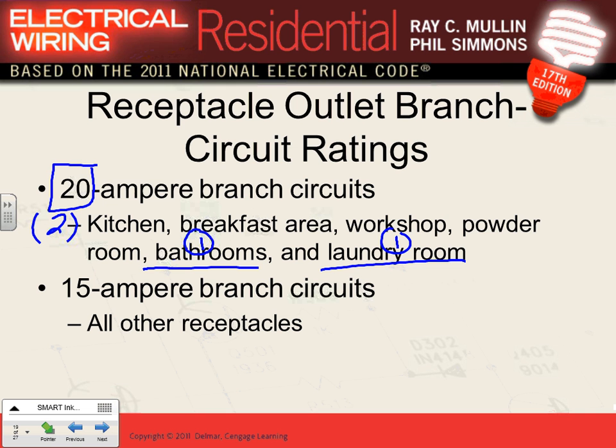Here's what you're going to be working on. These are basically the required branch circuits. Required 20 amp. I'm not saying 15 amp. Another 20 amp that also goes, typically we give a 20 amp circuit, if you want to write yourself a note, if you have a garbage disposal and dishwasher. These are highly recommended. Typically, we put them on the 20 amp circuits. We feed 1 from this circuit, 1 from the other circuit. Recommended. Can't emphasize enough. Recommended.